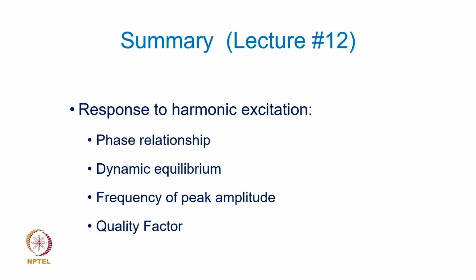Frequency at which the peak response is obtained, we also got an equation for that frequency, and then the concept of quality factor was introduced. The practical significance of knowing a quality factor for a given vibratory system has been highlighted.